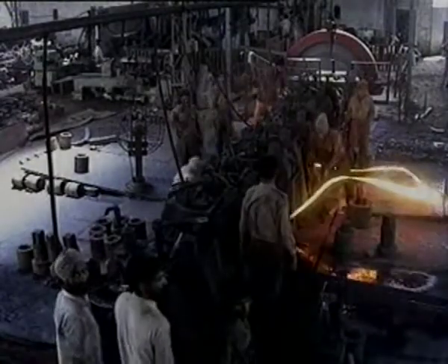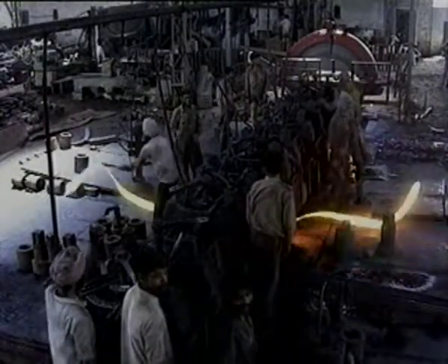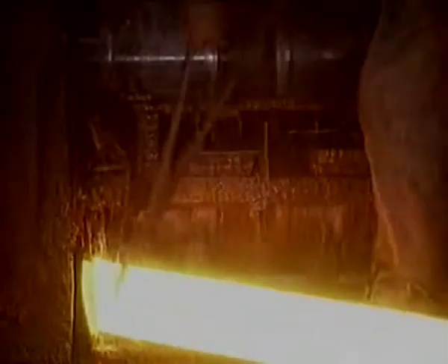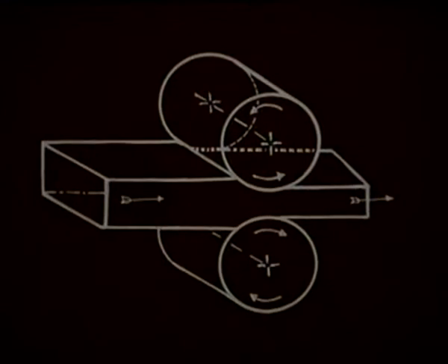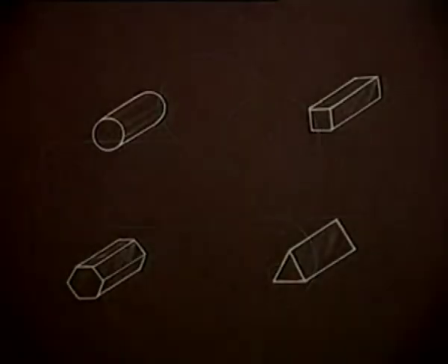Rolling is the process of producing different components by plastic deformation of work material by passing it between rotating rolls. The process is called longitudinal rolling if the forming rolls are rotating in the opposite directions and flow of work material is along the length of the job and perpendicular to the central line of the rolls. By this process, we can produce products like bars of different cross sections, steel for constructional work,